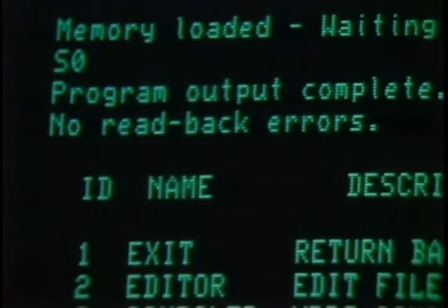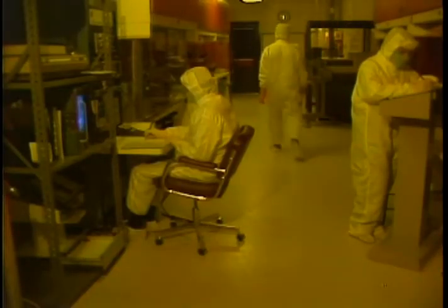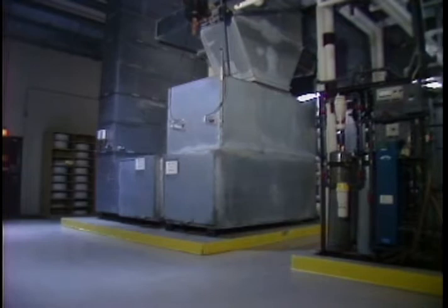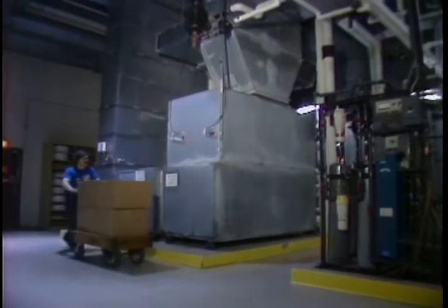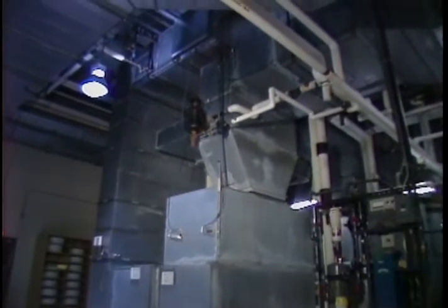Mastering and all other video disc processes occur in a Class 100 rated cleanroom. This means that the air contains less than 100 particles per cubic foot. This is cleaner than most operating rooms. Maintaining this working environment requires a mammoth investment in specialized ventilation equipment, ductwork, and strict adherence to clean room standards.